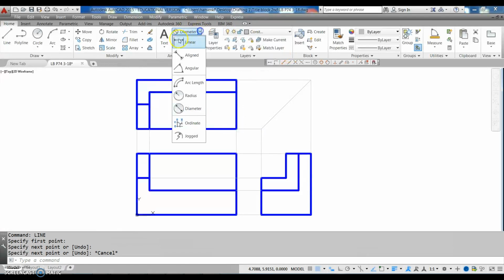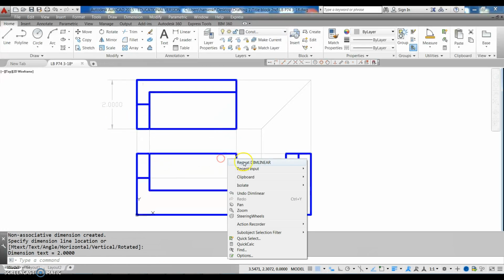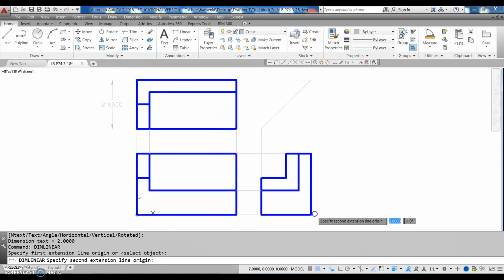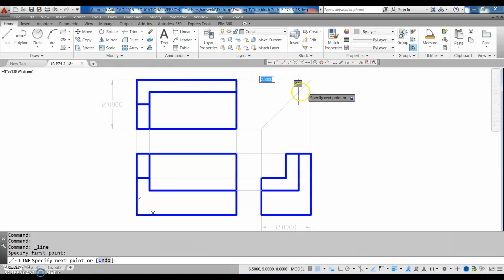The reason this is 45 degrees is because the top view has the same depth as the right side view, so therefore that creates a 45-degree angle. So now all of the lines that we have in the top view can come over and intersect the cutting plane line, and they should also project down. We're going to use this to project the circle in this view.